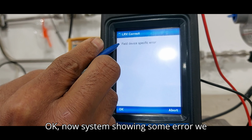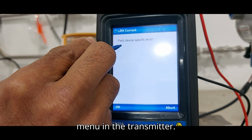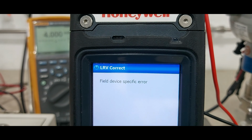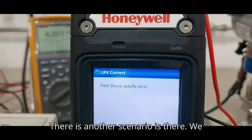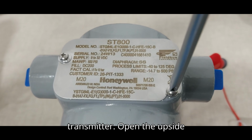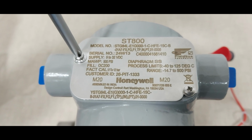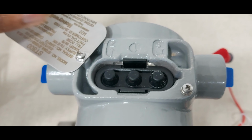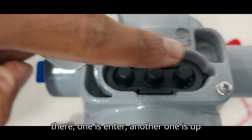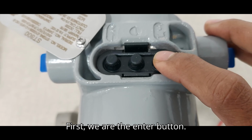Now the system is showing some error. We cannot access the trim menu in the transmitter. If you get this type of error message, there is another scenario. We will do the manual calibration in the transmitter. Open the upside screw, loosen it. There are 3 buttons. One is enter, another is up arrow and down arrow. First we press the enter button.